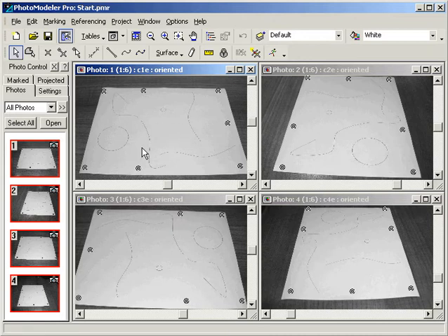These various curves demonstrate some of the variety of curves that PhotoModeler is able to model. PhotoModeler creates NURBS curves, which stand for Non-Uniform Rational B-Splines. NURBS are the advanced method for defining curves in 3D computer programs. There are 6 base points that have been marked and referenced already. We can see that the photos are already oriented. Photos must be oriented, and oriented well, before curves can be calculated in a project. It is very important to have the proper photographs if you want high-quality curves.